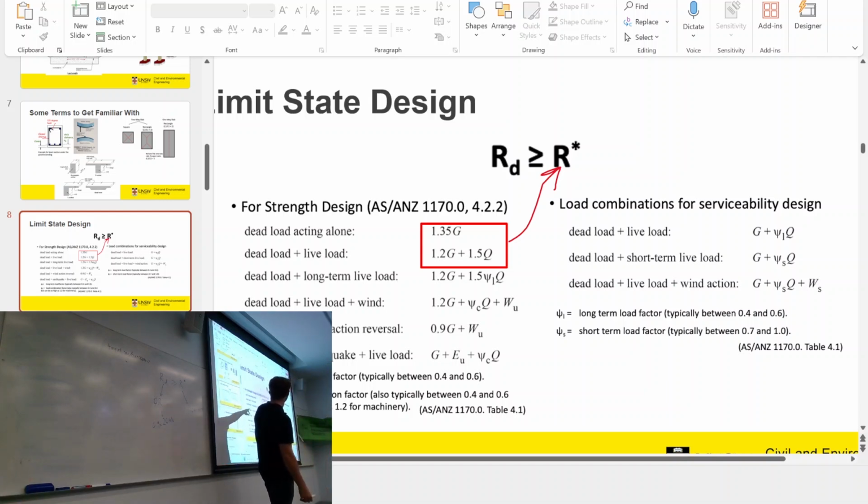Yeah, that's great. These are basically the only two load combinations that you'll use in this course. To be honest, I wouldn't even worry about all this other stuff. I don't recall table one using any of these ones here. Don't worry about it, you'll maybe use them in industry later. This one's important for other stuff, but you don't have uplift as much when it comes to deep concrete slabs. And then these are all your serviceability ones.